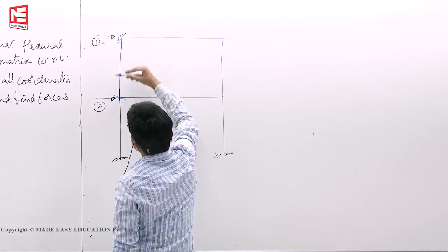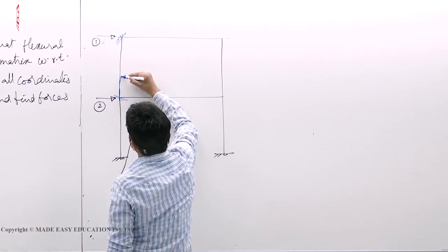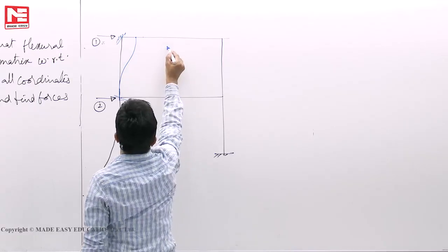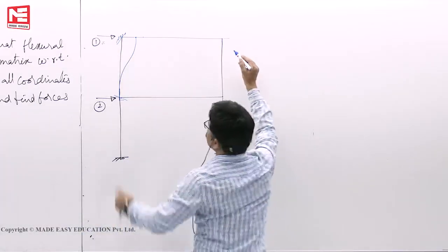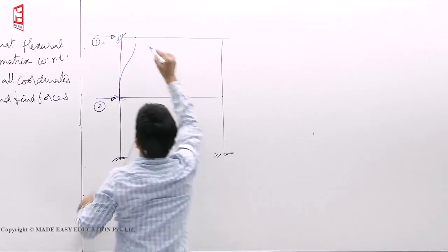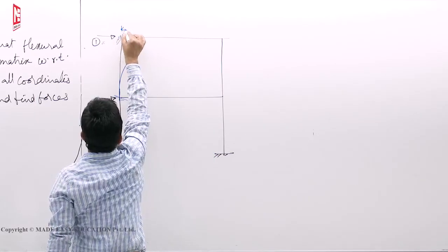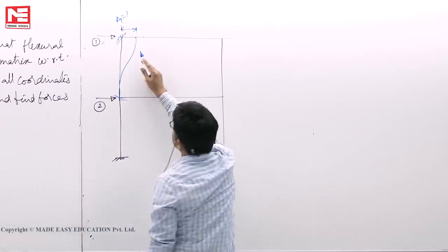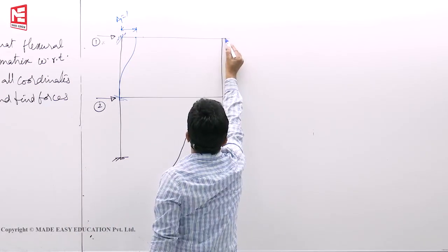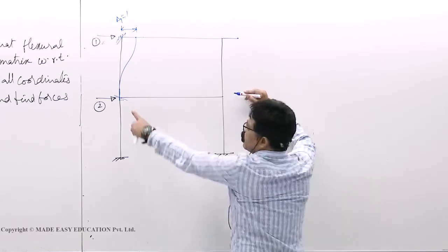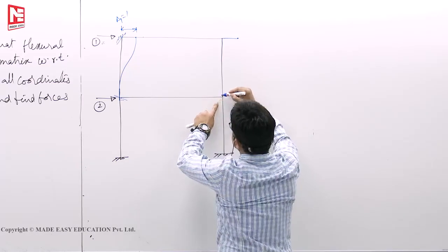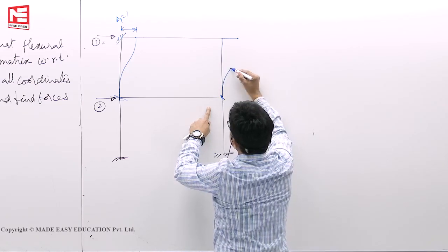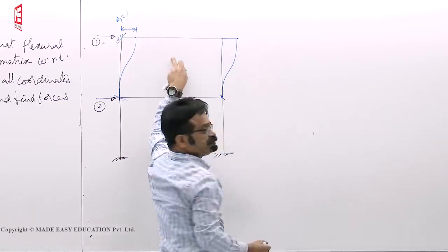So for this one, the deflection profile is like this only, because EI is infinity, given. You have to push it here linearly. This delta 1 is 1. If I push it as a rigid body, it will go also like this up to here. When I am fixing here, this also is fixed. It behaves like a fixed one. The deflection profile is like this.